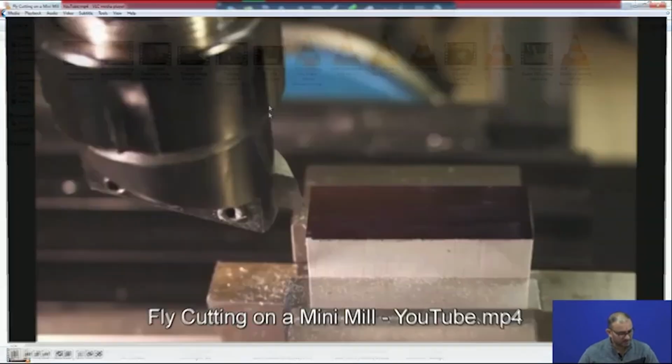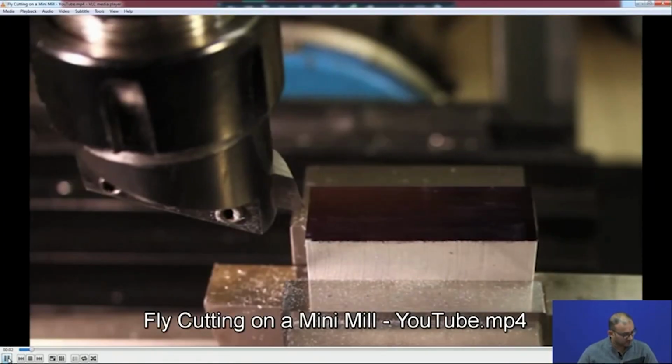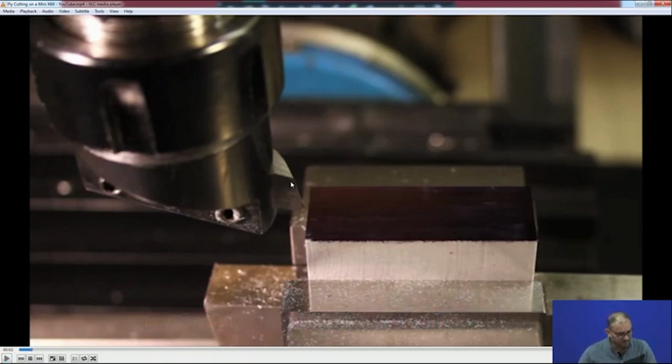Now, let me show you, this is the bigger conventional example. Now, you can see this is the workpiece and this is the cutting tool. So, it is a single point cutting tool, but it is attached with the spindle axis of the machine, and then it rotates. When it rotates, it has only single cutting edge which will remove the material. So, to get this thing done, you have to rotate this thing at a high RPM and a very low feed rate.